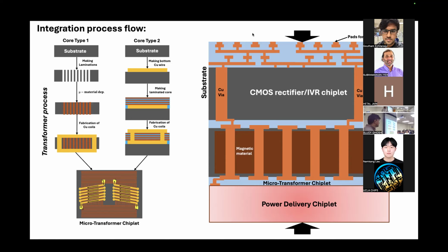So if you are using a thin film process to build this, you have to do so many layers to get that volume. That's going to be a very expensive process. You have to do metal, insulator, metal, insulator, one after the other. Imagine doing 100 layers of that, building several microns with each layer being just 200 nanometers. You may have to do this hundreds of times. But here you can potentially do it in just one shot.